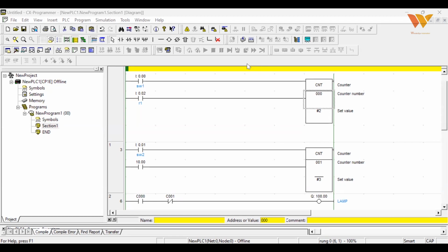Yes, it is a sensor, ma'am. That's why I used Y2 as a NO. Then I used Y0 as a NC. With these conditions, I make the Y1 output. And simultaneously timer T2 for 10 seconds. Here, all this Y, whatever is there, even if it is a sensor, it is output only. Here we have considered it as output only because we're indicating it.